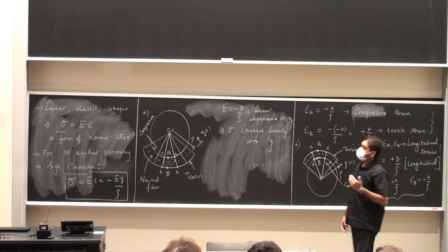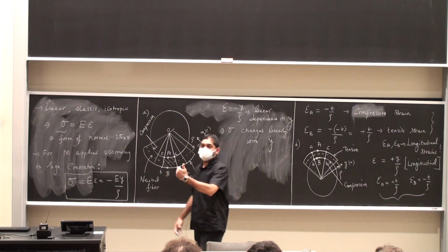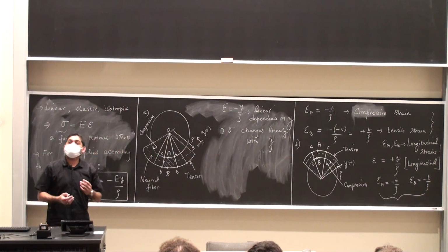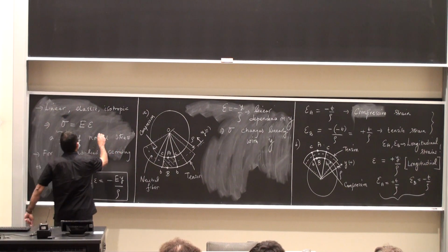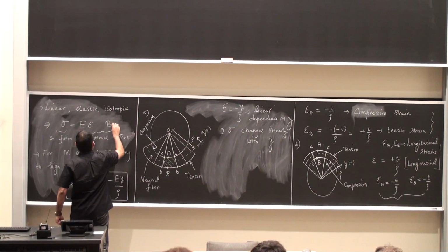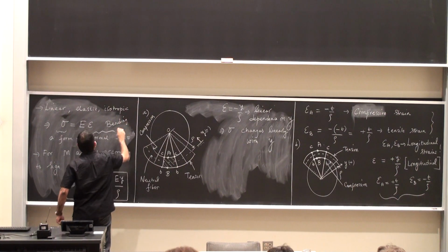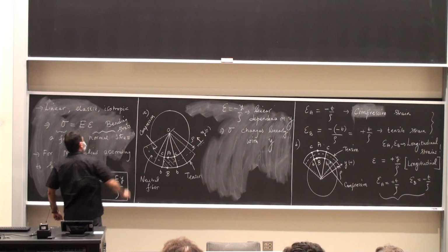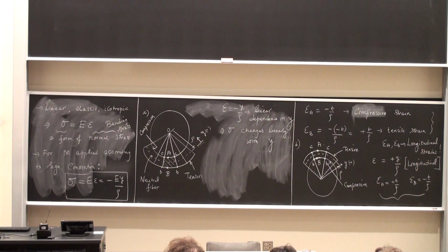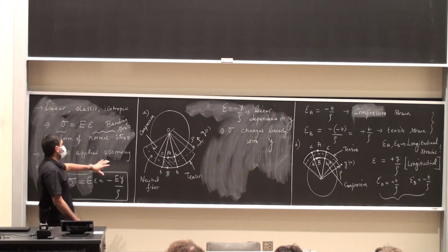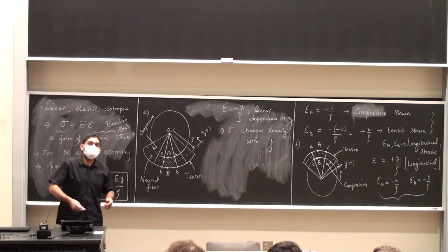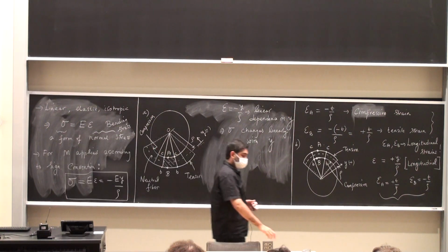What is the neutral fiber? The fiber where there are no bending strains, which means there are no bending stresses there either. So this is bending stress. And I want to draw its evolution by looking at, for example, this beam here. How does it look? How does it evolve? It evolves linearly, we know that.